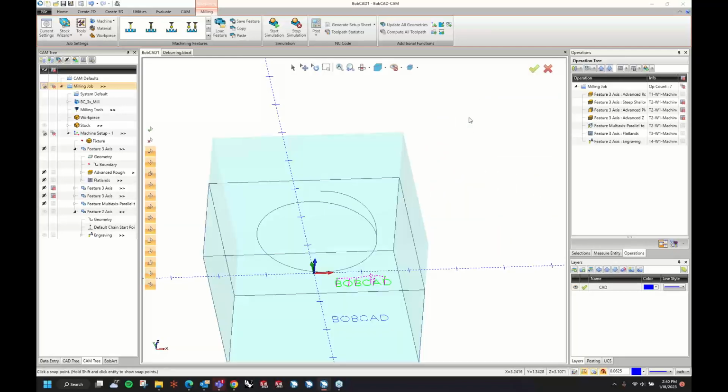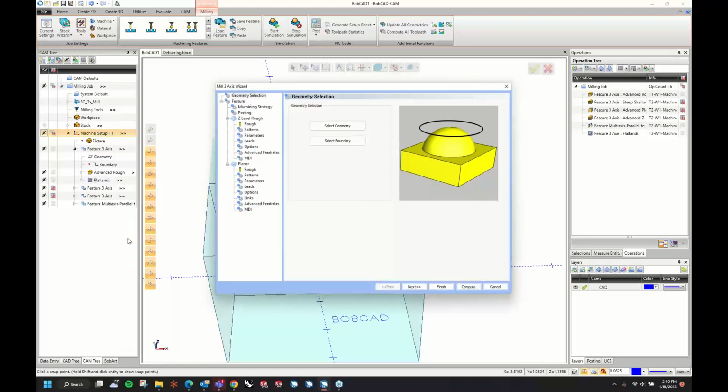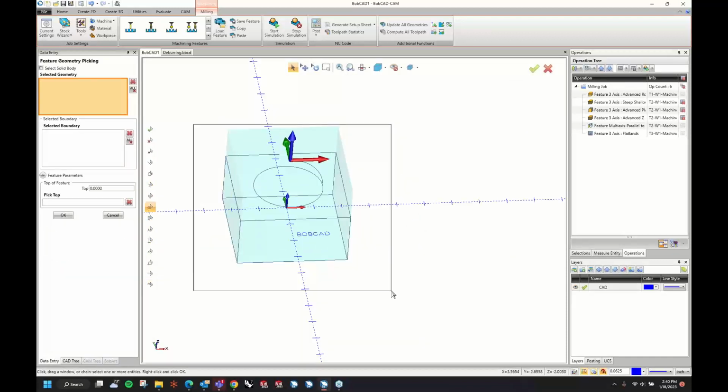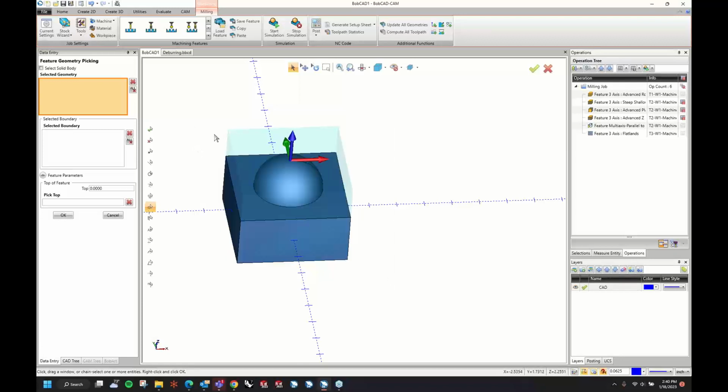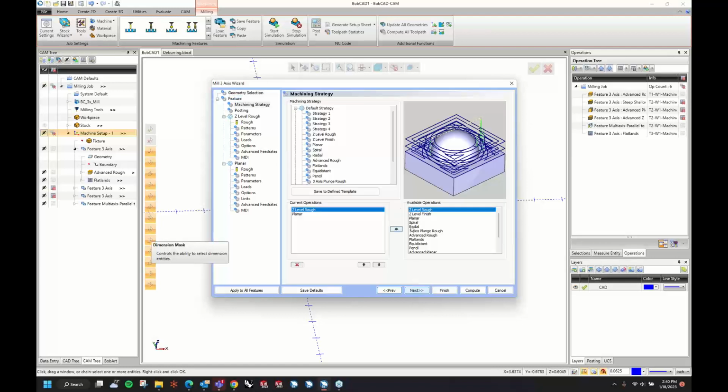Now, I will say, John, if you're engraving on something that's radiused and you need it on like a solid, there's actually a really cool trick that I use. I'm going to delete this. Let's say you have to do it through 3-axis, like it's on a curve. Let's just add a 3-axis feature here. There's a type of path under 3-axis. That's the project curve path.